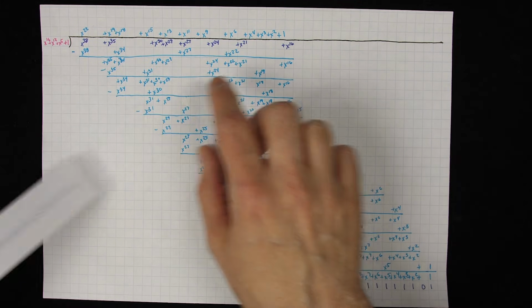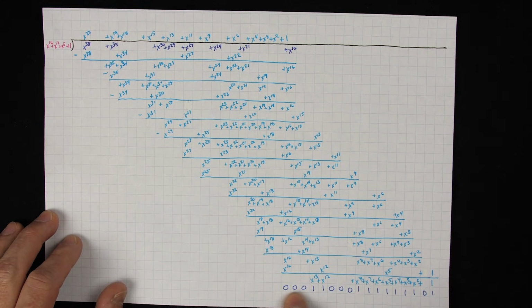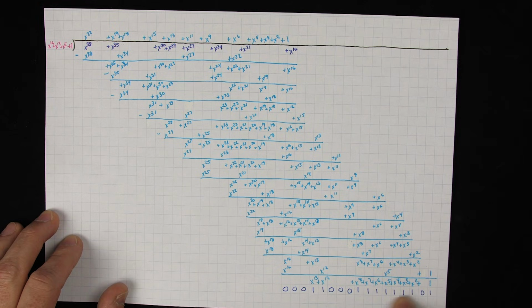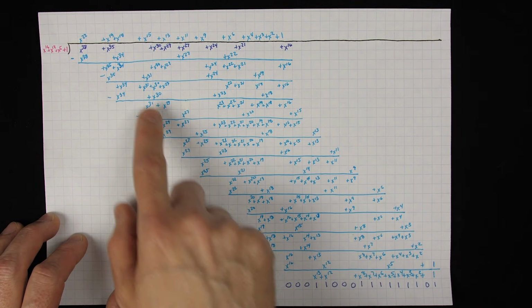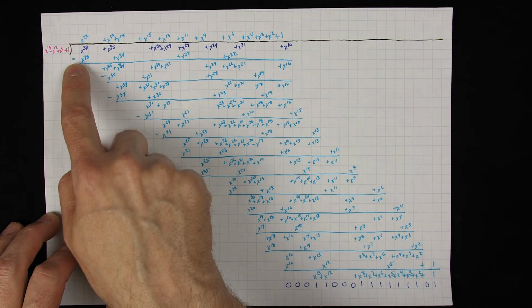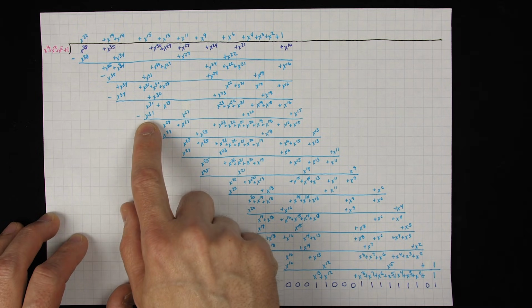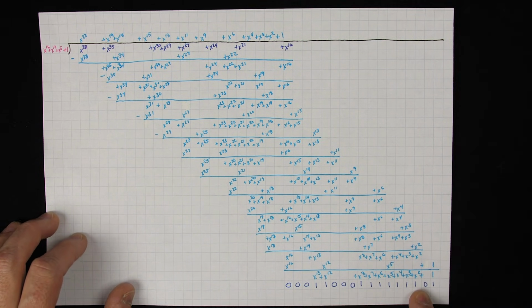And so how do we get from this polynomial that we start with that represents our message down to this 16-bit value that is our CRC? How does this process actually work? Well, it looks like we're doing a bunch of subtraction. So each step along here, we're subtracting something. We start with this thing representing our message, and then we subtract something, and then we get something, and then we subtract something else from that, and we subtract something else from that. And we just keep doing this subtraction until we ultimately end up with our CRC.